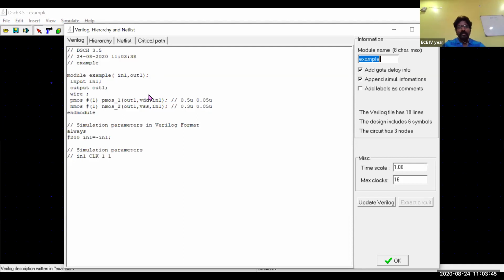If you see the syntax of Verilog, you have a module, then the module name comes, and inside the brackets you give the input and output. There are different styles of writing Verilog code. In companies, mostly the output is written first and then the input, but there is no problem writing input or output first. First module, then the module name, inverter, which has been taken by default as an example. We have only one input and one output, so first input and then output.